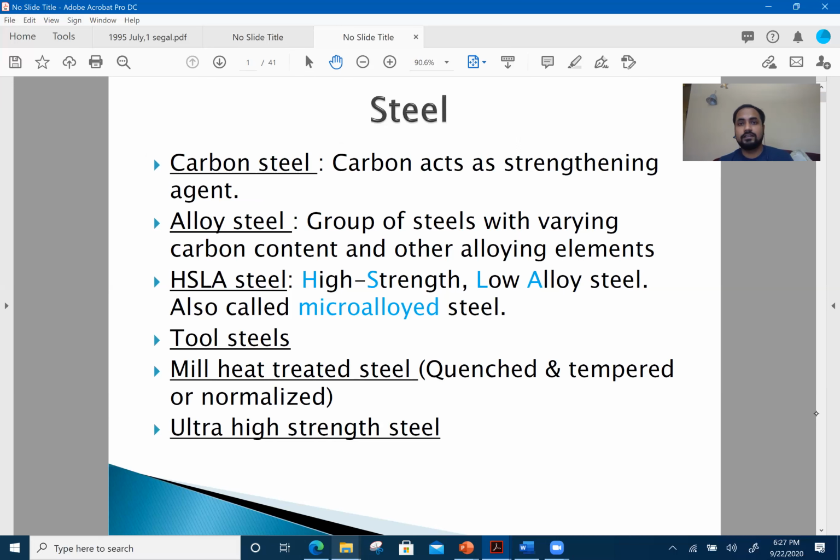You can look into stainless steels. Now for normal carbon steel, we talk about the iron carbon phase diagram. For stainless steel, carbon is really low, a very small percentage. So for stainless steel, the iron chromium phase diagram becomes really important, so you can look into that as well. If you want, I can help you understand stainless steel much better. Then we have tool steel and all other kinds of steel. But I think with this discussion today, you might have some understanding of where to begin and how to search for different kinds of steel.